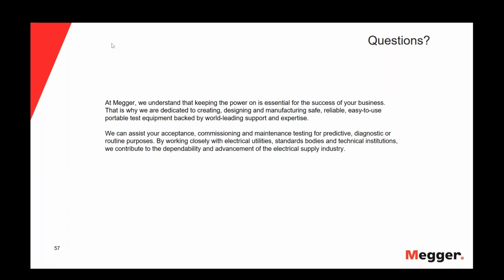And this is a kind of a Hail Mary, okay? So everything failed. They started with the normal test. They knew it was a troubled cable. They reduced it to 2U0. It failed during the 60 minutes. Now they do 1.7U0 for 5 minutes, and hopefully it passes. And now understand this. This is not really a proper withstand test anymore. This is just, oh, we have a really troubled cable, a bad cable. They just do some test to be sure when they re-energize the cable it's okay, and they would immediately schedule that cable for replacement, because 1.7, you know where this number comes from, is the over voltage factor for the ground fault. So they just want to make sure, okay, if I turn the voltage back on the circuit, it's not just going to blow the fuse again and trip. So that's a typical procedure.